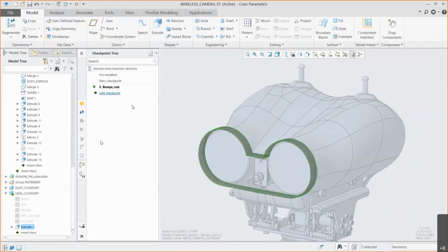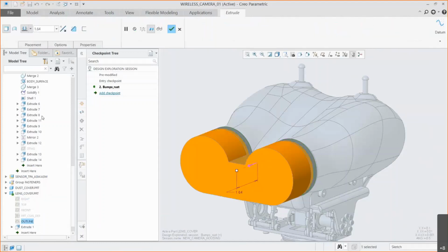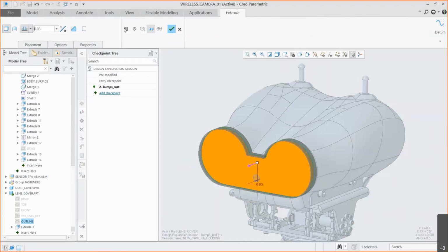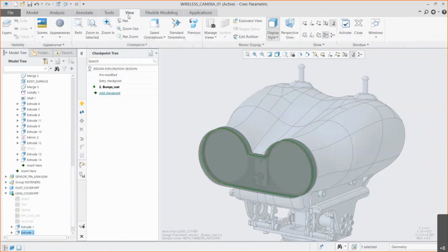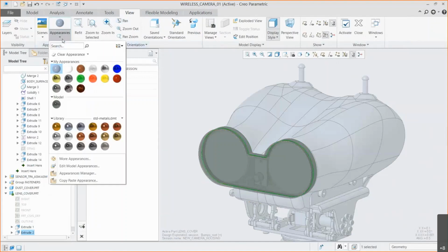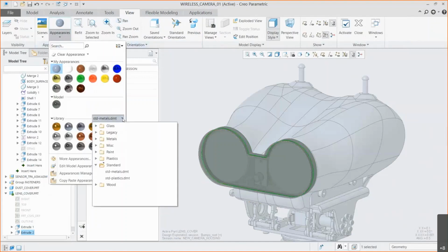But like I said, Creo allows you to start simple, right? Click that simple extrude. It gives you a preview in orange, and it starts you with a unit, and then you make the changes as you need to. So it's fast, it's easy, and if you don't need to get more detailed, it's just a couple of clicks. If you do need highly detailed, nitty-gritty control, you have those in those further menus. So really a great way to streamline processes for a lot of different people who need different things out of different tools.